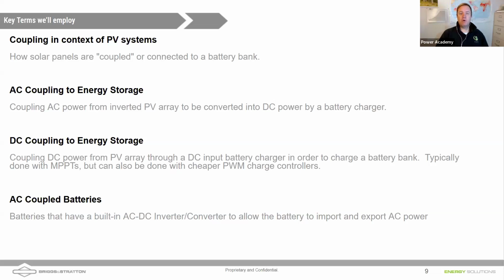Nathan, I did want to make one point. On specifically Enphase, everybody kind of liked the Enphase microinverters. I know I did, and I kind of still do. The idea is that you get module level monitoring. They have optimization, or the ability to not be impacted by shading. And also to be able to string together the AC conductors and just bring AC off of the roof.